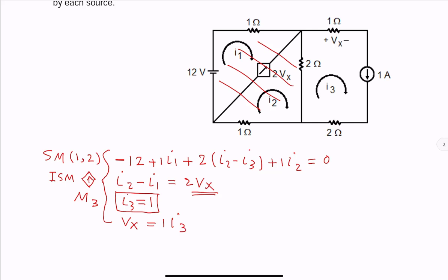Quickly check for a sign mistake for terms involving resistors. I have mentioned this in previous videos. Since we are using voltage drop, for Supermesh 1 and 2, we should get positive I1 or positive I1 minus something else, positive I2 or positive I2 minus something else, meaning another current.